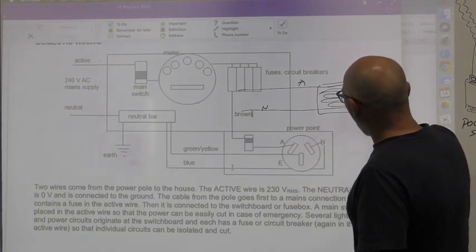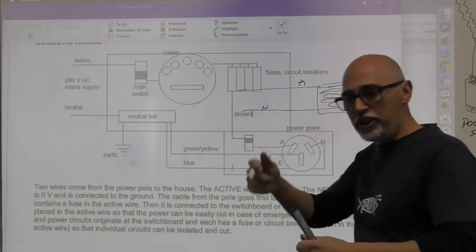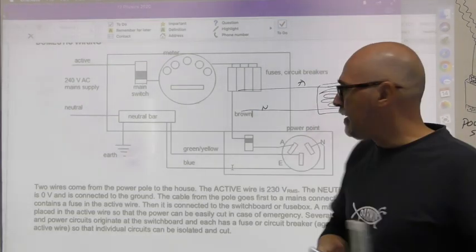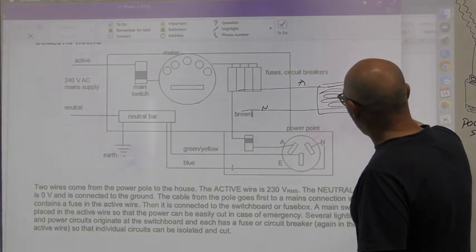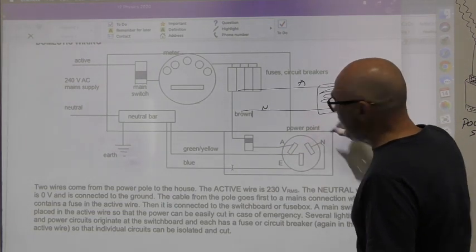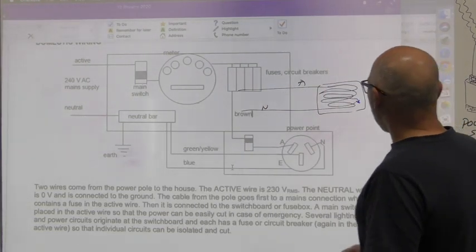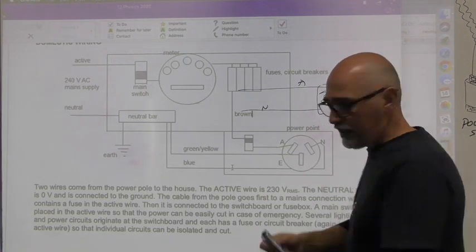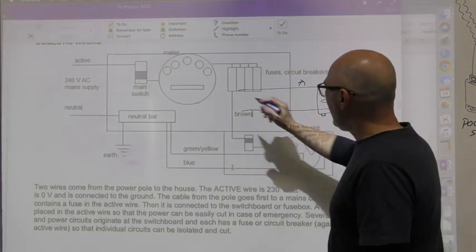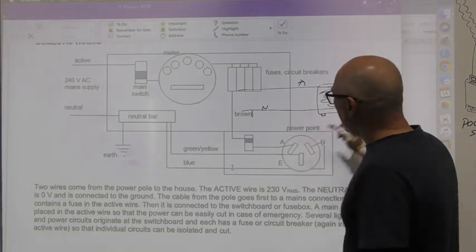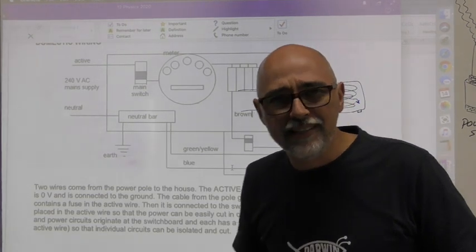just in case this wire here breaks somewhere along in its operation, and all of a sudden this active makes contact with the outer skin of your toaster. Okay, now if it makes contact with the outer skin of your toaster and it's got like some nice little rubber feet so it doesn't slip, then technically there's nothing happening there except until you come along and touch it.